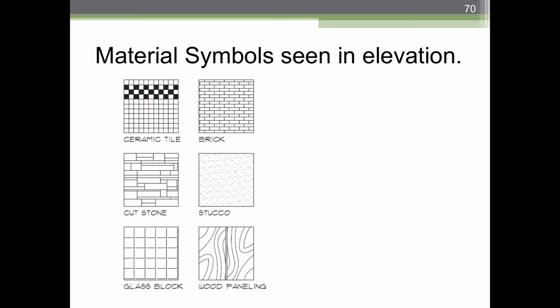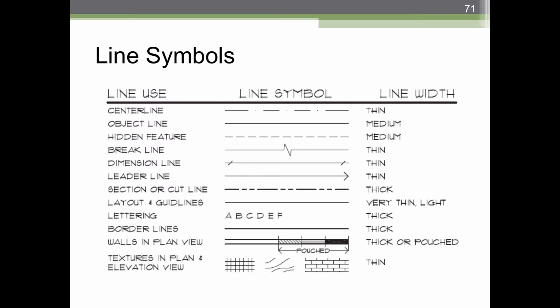Once again, Revit can help you out in this, and there are ways within Revit to use custom hatch patterns. You might say, but why don't I just render it? Wouldn't that be a lot easier? Construction drawings are never rendered. Okay, there are times where you will show renderings to contractors and subcontractors, particularly for intent, but construction drawings are basically never rendered. You use hatch patterns. And again, I think there's a logic to it in terms of showing them something generic and then specifying a product in the specifications.